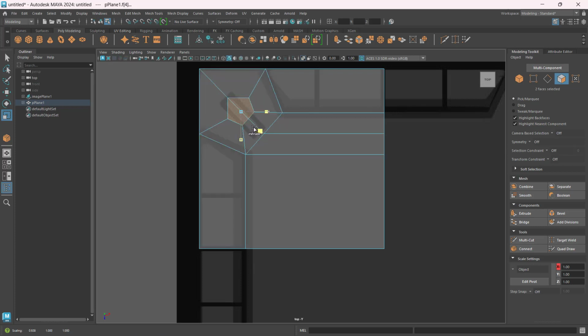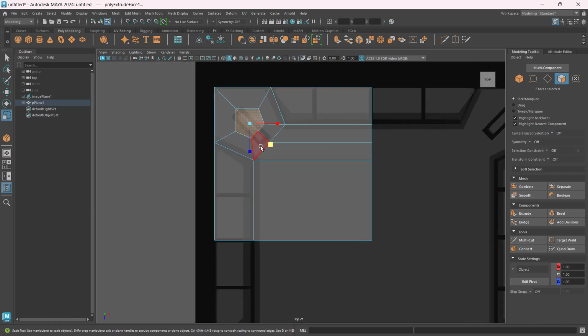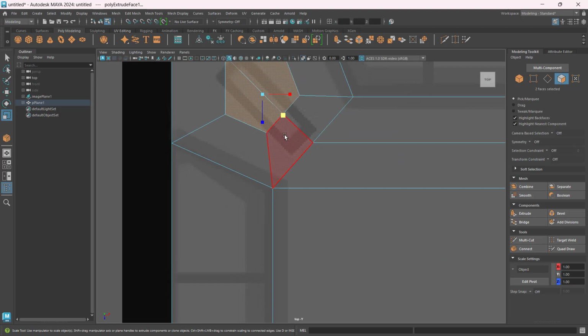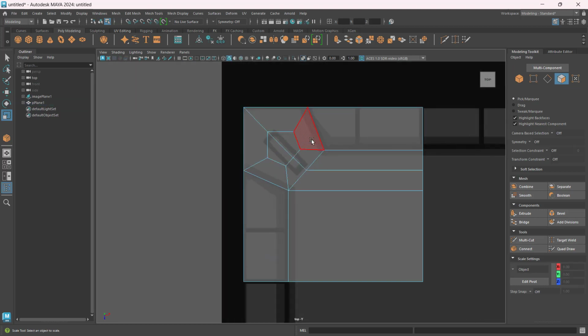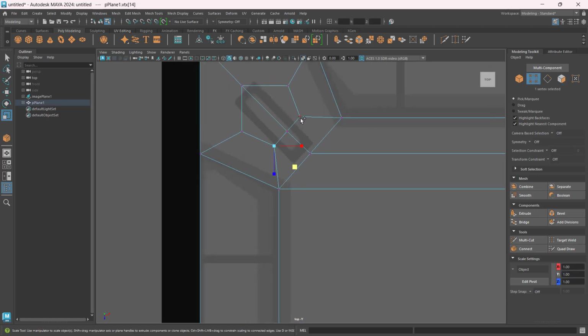Shift click drag, and there it is, right? So now what I will do next is I'll just go to my vertex selection. Oops, sorry. W. And then I can just R, scale this together in, and then I can just move and then just drag them along here.